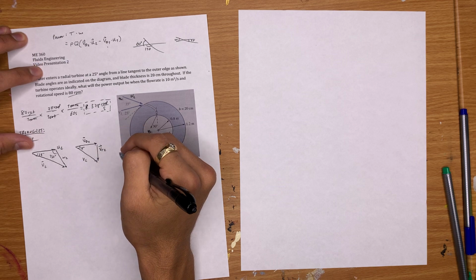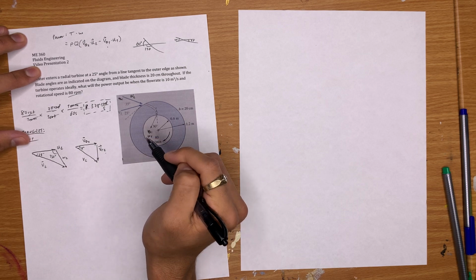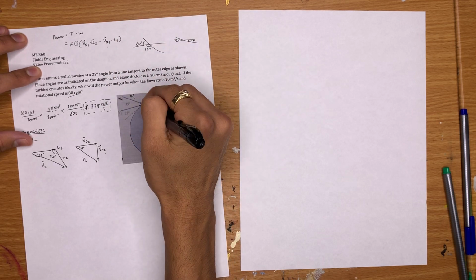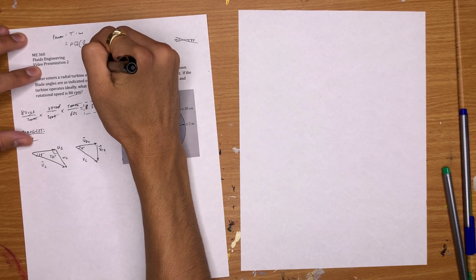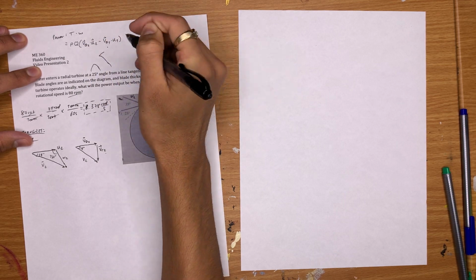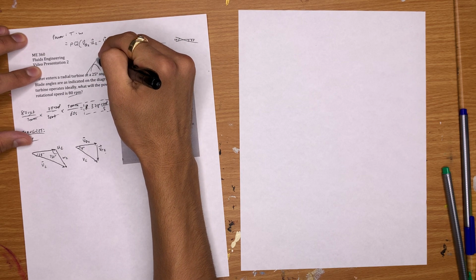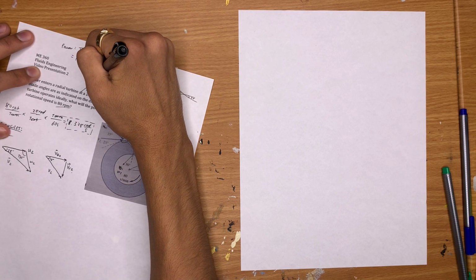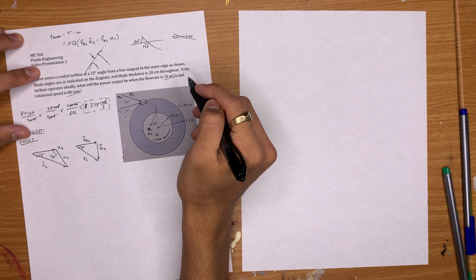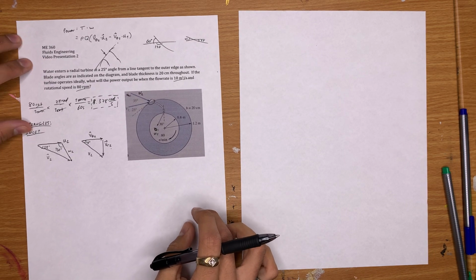And if you notice, we can define V theta 2 in terms of VR2. The reason we want to do this is because let's say we zoomed into this spot here, and this is what it looks like, the inlet. If we have a tangential direction at this point here, that means that the radial direction can be found from the flow rate. This velocity has to do with the flow rate. I'll show you how to do that in the next few steps.